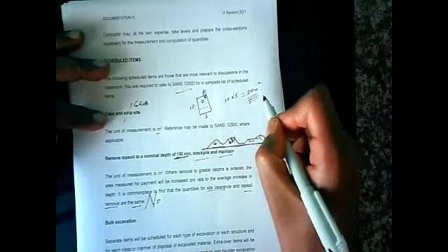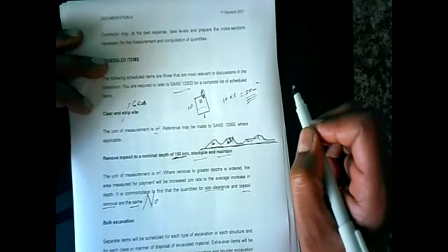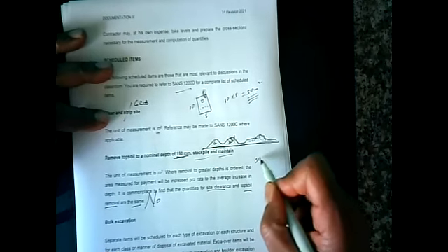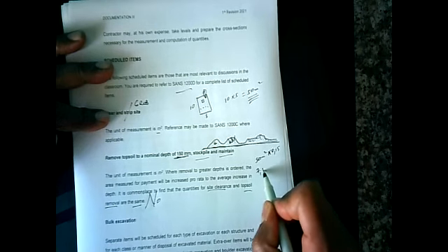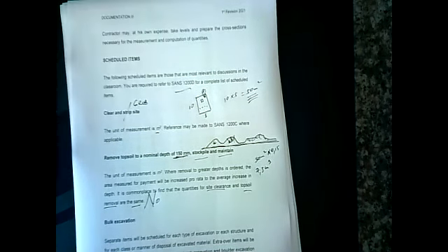No, I don't like that. Because if that was our area of clear and grub, let's put some numbers to the topsoil. 50 meters squared times 0.15 gives me how much? 50 times 0.15, 7.5 meter cube of material.